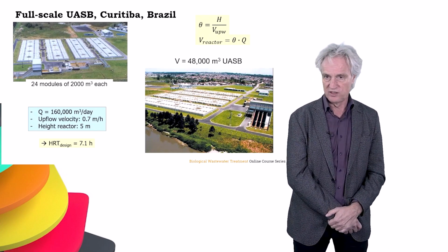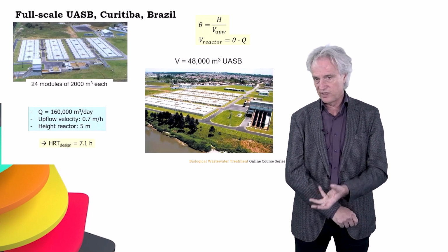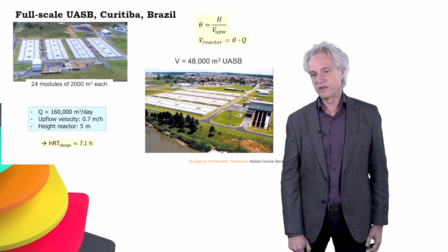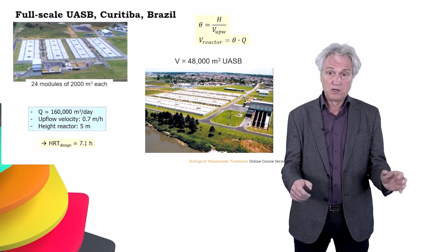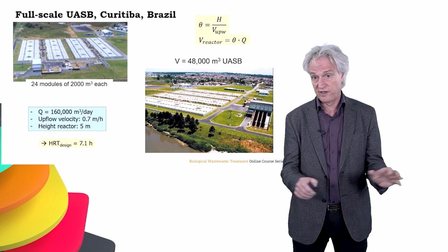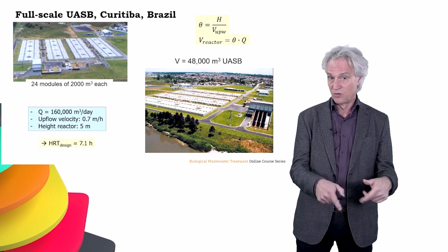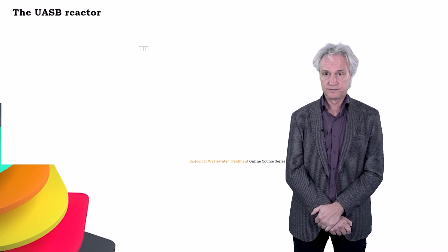Interesting is also the Archimedes screw influent pumps that bring the influent to a high level, and for the rest the entire plant is fed by gravitational distribution. So hardly any energy is used in operating this plant. Moreover, you generate quite a lot of methane gas.